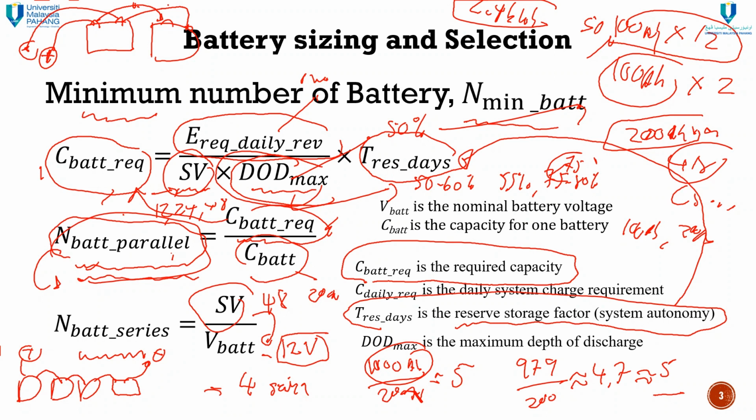That one is very dangerous. Sometimes we use a breaker in the middle. With a breaker in the middle, at least we can isolate while connecting the wire, while doing the parallelizing, so at least they don't have any running current between the batteries. That is quite risky if we use parallel.